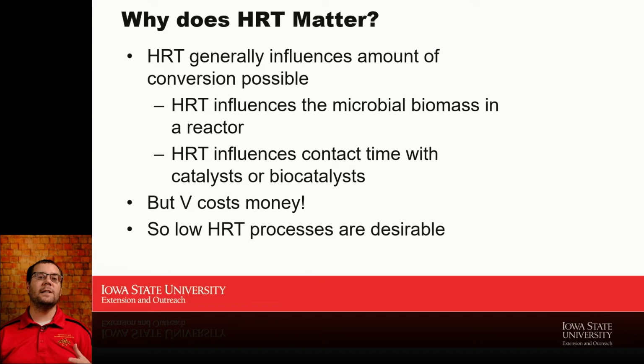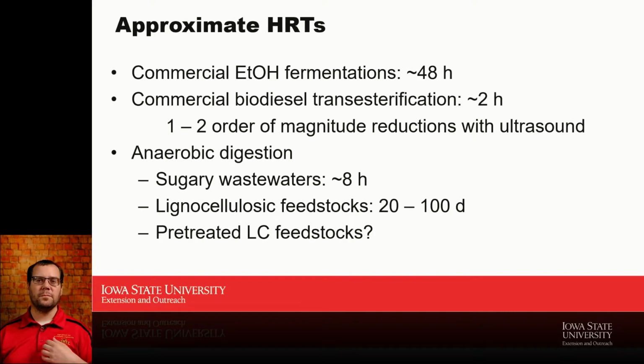So really what we're trying to do is balance those two so we can consume it as quickly as possible, but still get a relatively high conversion rate of whatever we fed and get it broken down. In general, if we can design systems that have low hydraulic retention time, that saves us money because the tank is smaller, but we do often pay for that through adding sophistication and more challenging management to that tank we've built. I promised you I'd talk a little bit more about what some hydraulic retention times are.